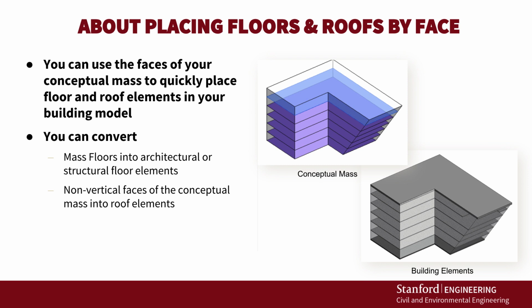You can go through and place floors, roofs, walls, and curtain systems. But in this section, we're specifically going to be looking at how we place floor and roof elements using your conceptual mass. Now you can convert mass floors in your conceptual mass into architectural or structural floor elements. You can also convert any non-vertical faces of the conceptual mass into roof elements. So let's take a look at how you'll actually do that.